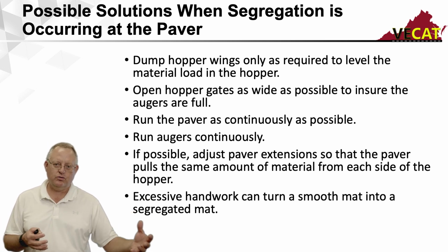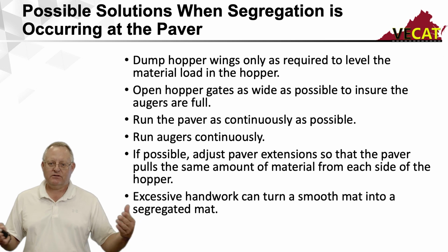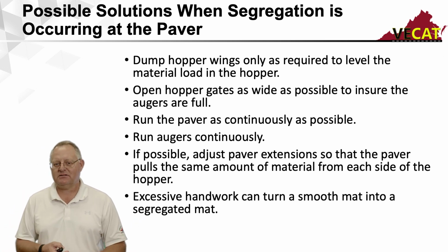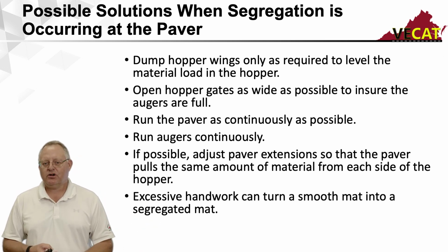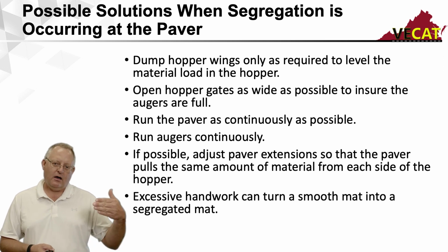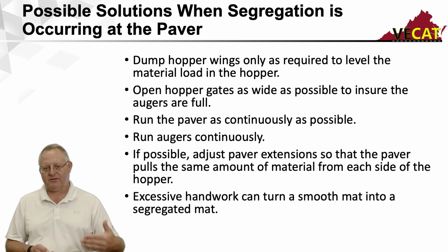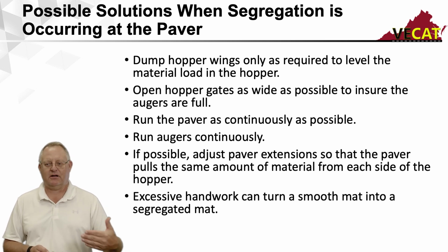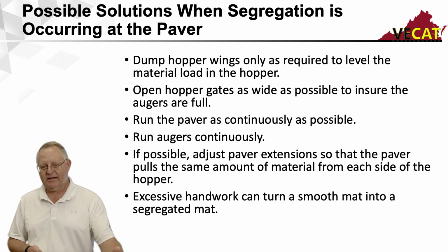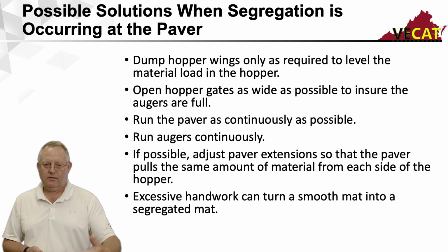We're letting it cool, or we're moving it too much. So again, this goes back to the experience of that ground person controlling that hopper. Are we running the augers as continuously as possible? Are we running the paver continuously? Are we making sure that the screed extensions on the augers...